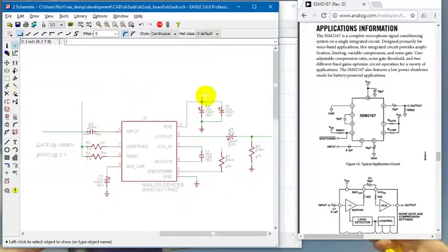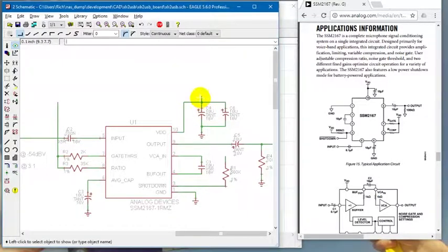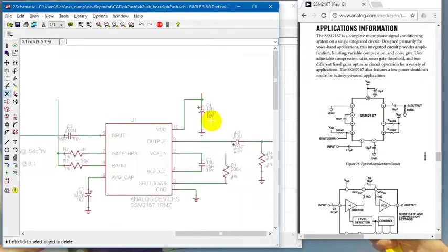And we will do something similar with the power lines that we haven't built yet. So let's get rid of that extra capacitor that I don't really need. I will actually connect another capacitor next to it. It's not on the schematic, but this is something I always do. Whenever I build something, I build a high frequency cap and a low frequency cap, but we'll get back to that when we do the power supply and stuff like that.